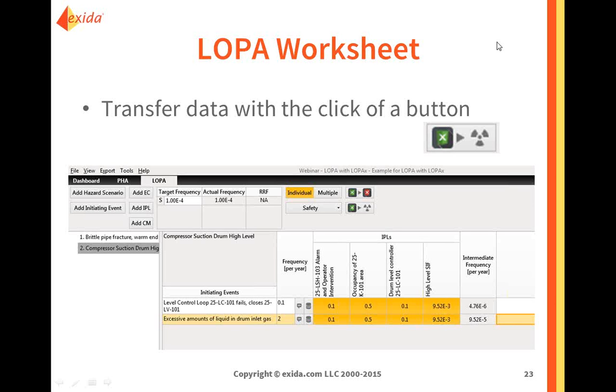They have common equipment, and you would need to consider doing a detailed evaluation on that combined protection layer of the control valve and the operator action. Because they're responding to the same measurement and the same signal generated by the controller, you cannot consider them two independent protection layers. I'll try to get a slide in for the afternoon session, where I will show that.